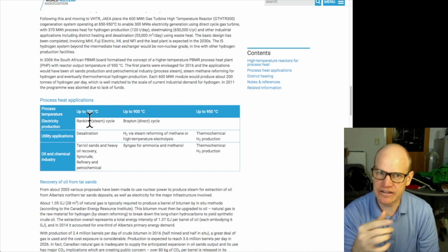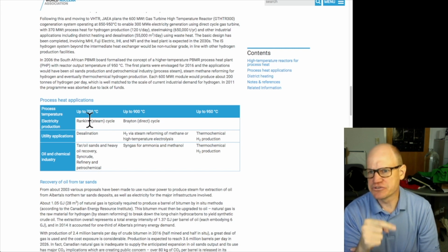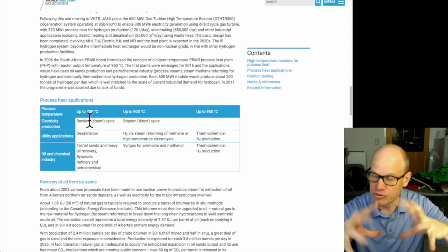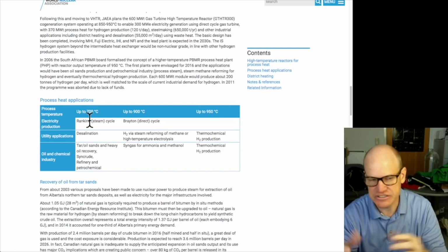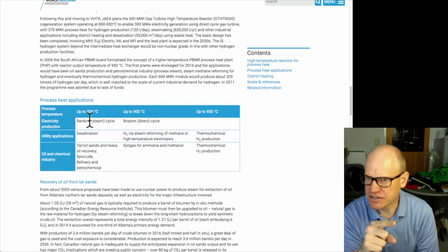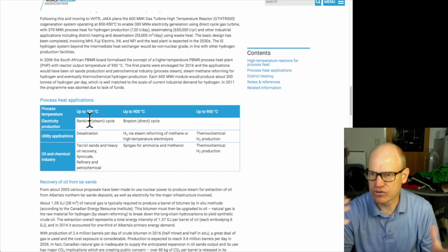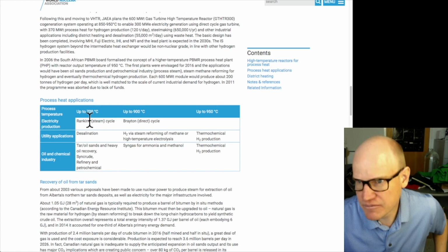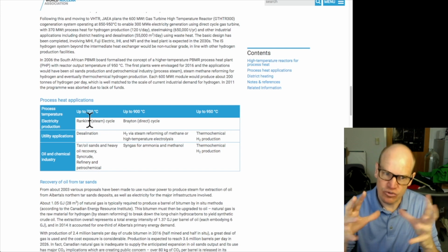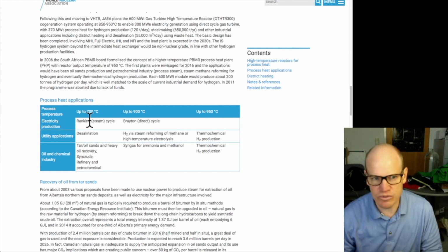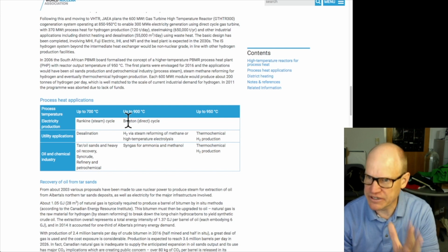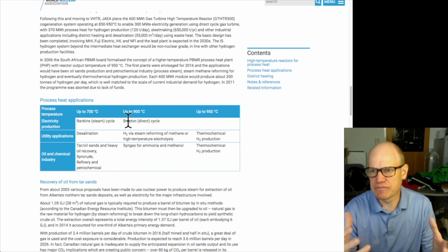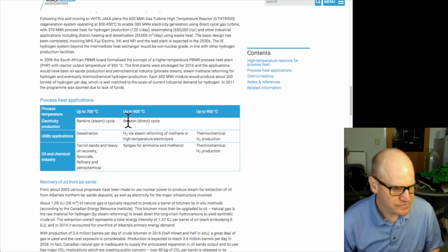However, if you're backing up renewable energy, you can't use that cycle, because it takes a long time to get the cycles working together, where the boiler for the steam cycle is operating efficiently. It doesn't ramp up fast enough for when the sun sets. The sun sets over the course of an hour, hour and a half, and it takes longer than that to ramp up a typical combined cycle power plant. So the peaker plants that deal with intermittency in renewables are the direct Brayton cycle with no combined cycle component. There are always companies working on improving these things, so that might change in the future, but for the moment, this is what's going on.